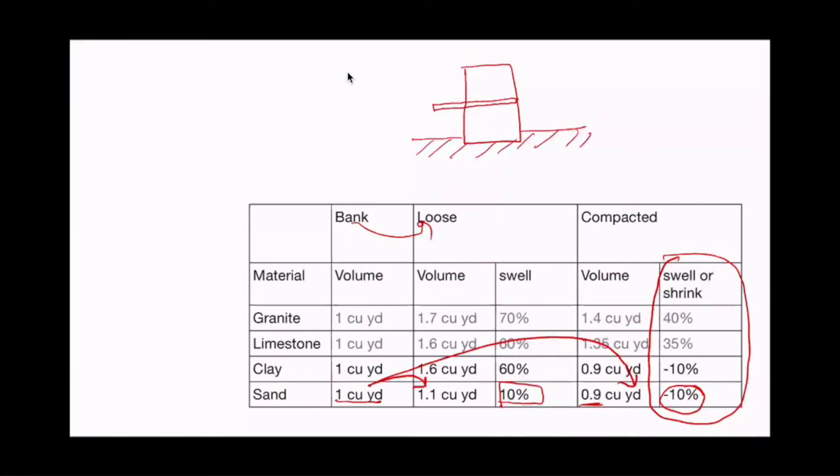If that steel is exposed to outside, and outside it's 0 degrees and inside is 70, you can imagine how that steel will get cold on the outside, and because it's the same piece of steel going all the way through, it will actually bring that cool inside the building. So that steel will look warm to the outside and cold to the inside, because the temperature of that steel right here may be 50 degrees, and the temperature of the steel just inside the building may be 52 degrees. So you have a 52 degree piece of steel inside a 70 degree building.